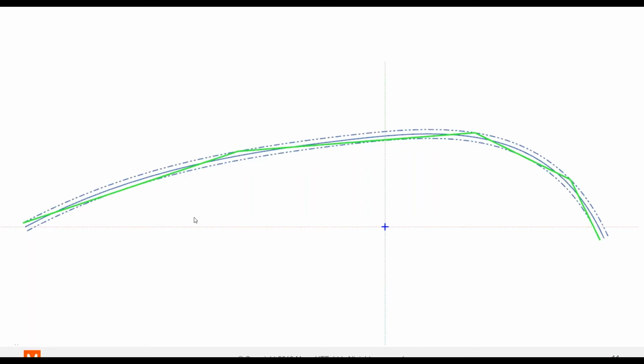So the question is, what happens if this is a zigzag toolpath and I've zigged over to the right and now I'm coming back the other direction? And it looks like this in red. The red is also a valid toolpath. As you can see, it does not violate the in-tol or out-tol. However, if we look at localized areas like this one right here, we can see that the out-tol state in red is just adjacent to the in-tol state in green. When we look at that situation over an entire surface, we'll notice it as a rough surface finish.